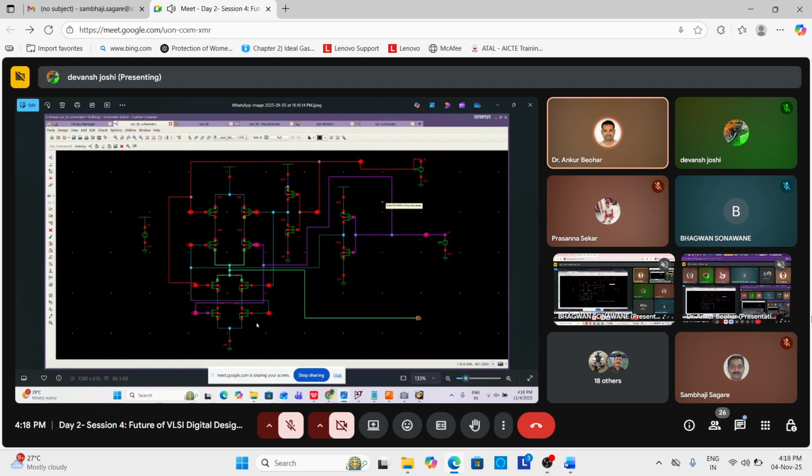We have XOR, encoders, multiplexers, I mean 2 by 4, 4 by 8 like this. And then you can go for some medium level circuits also, like SRAM design, static random access memory. Here we have not discussed it, but SRAM, you know well, is not quite complicated. Like a CMOS inverter design, we can design 6T, 9T, 7T SRAM, where T means transistor, basically 7 transistor, 6 transistor or 9 transistor like this. Read and write operations you can achieve.